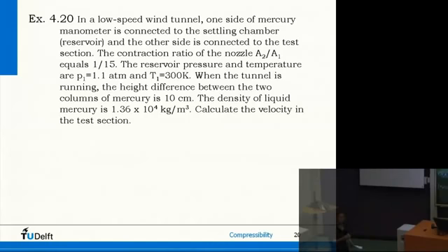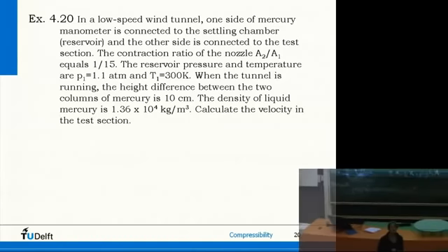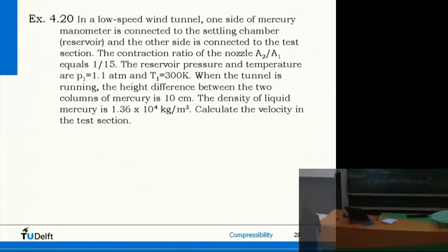The equation of state, perfect. If you think about the isentropic flow relations, P over P and T over T, that's really for compressible flow, where you have significant temperature changes. In incompressible flow, you typically don't have them. So the one I used before for the supersonic wind tunnel will not get you anywhere. But the equation of state, P is rho RT. So if we know pressure and temperature somewhere, we can find the density. Do we have pressure and temperature somewhere? The reservoir, or, well, the settling chamber it's called here.